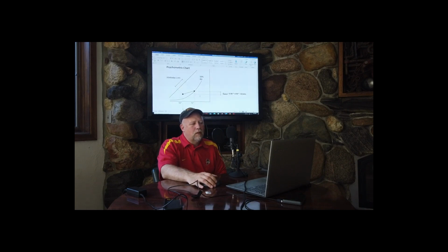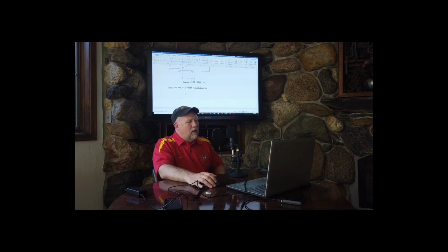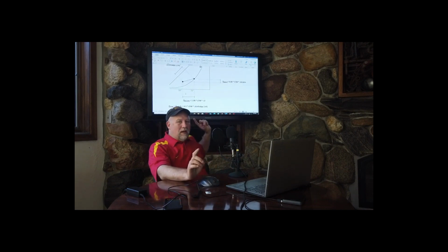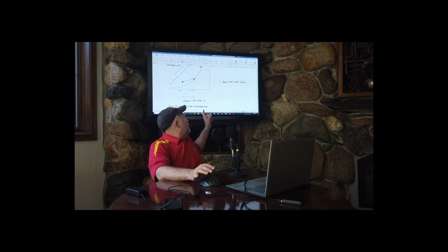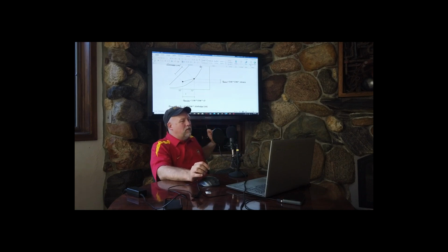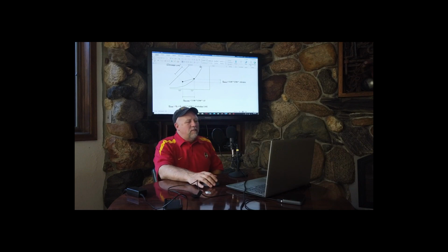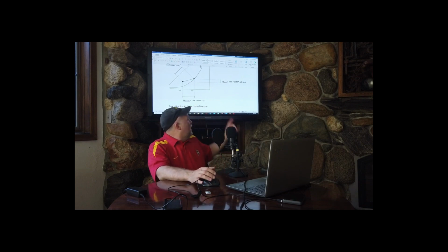Back to, here we go. So I can use this equation, new equation, write this down. You need all three of these. These are three key equations as we're using the psychrometric chart and calculating air conditioning loads. Sensible, latent, and then adding those together is total. There's another equation. 4.5 times CFM times the difference in enthalpy.